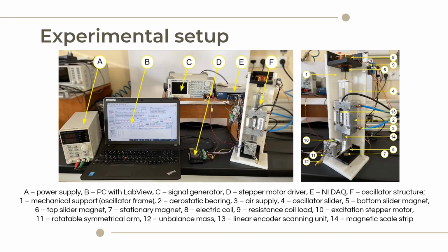Here a constructed laboratory stand is presented. All control and measurement signals are managed by the National Instruments Data Acquisition Device and LabVIEW software. The oscillator displacement is measured using linear magnetic encoders. In the photo on the right, you can see the main mass of the oscillator, number 4, and the aerostatic support, number 2,